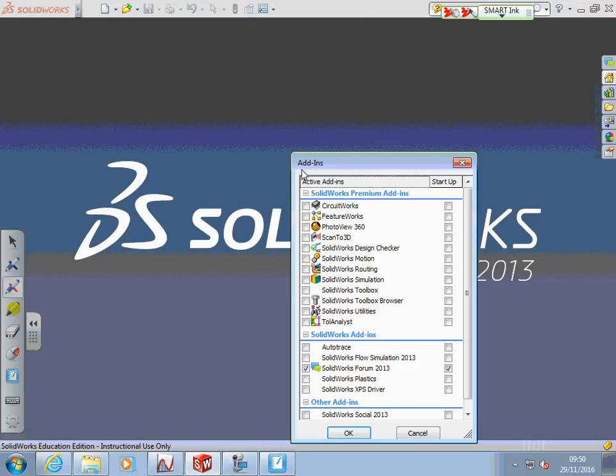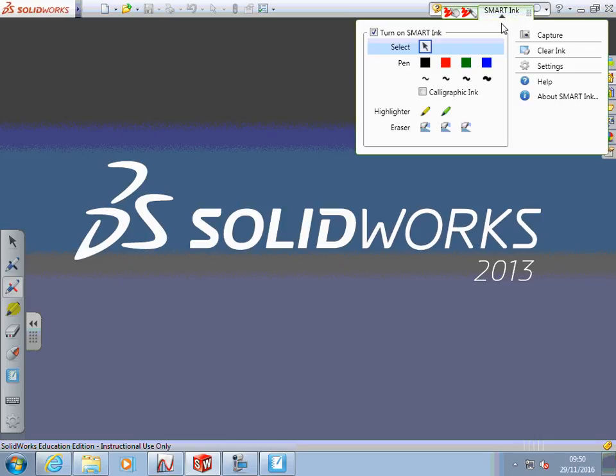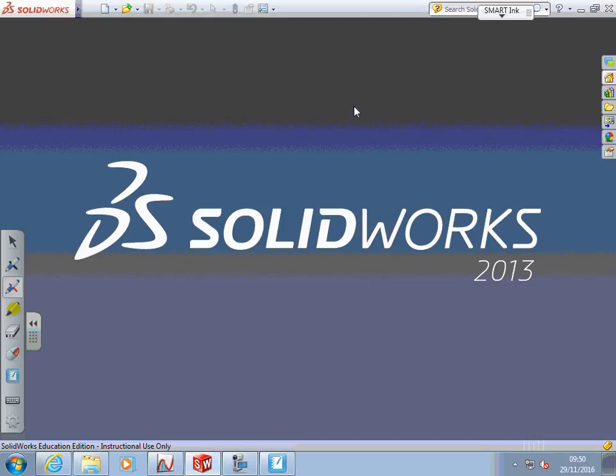Click add-ins, and then the add-in we want, we tick this box on the left here to load up SolidWorks Simulation, and OK. If you get any dialog boxes up asking for acceptance, please say yes. Accept.